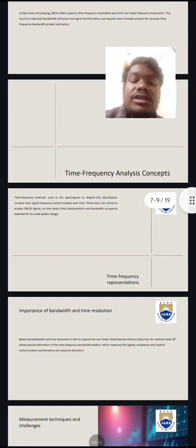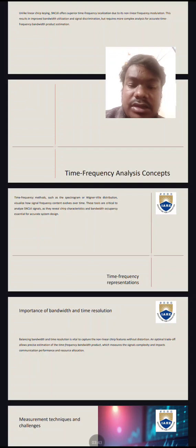Time frequency analysis concepts. Time frequency methods such as the spectrogram and Wigner-Ville distribution visualize how signal frequency content evolves over time. These tools are critical to analyze essential signals as they reveal chirp characteristics and bandwidth occupancy, essential for accurate system design.